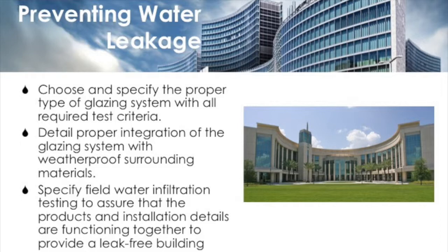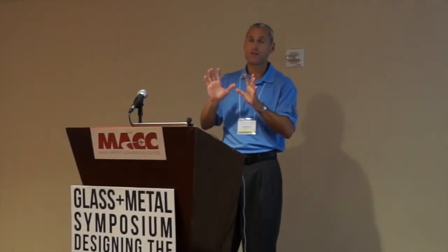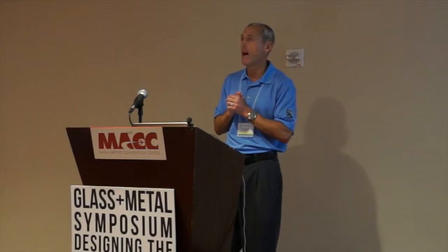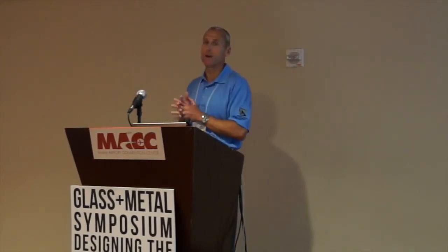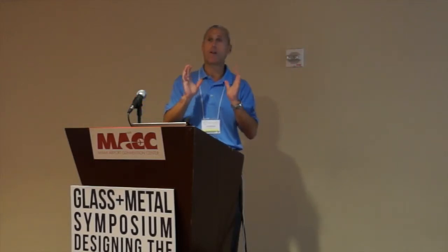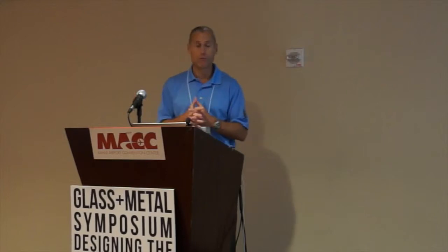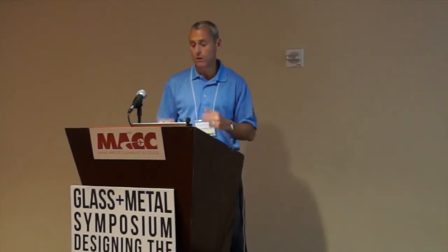And then, in my opinion, and what we do all the time, is specify field water infiltration testing, like the demonstration we're going to see outside. Because the field testing can test the system as it's installed on the job and how it integrates with everything around it. So we're expanding that scope out from just the glazing system to how it integrates with the actual building, how it's going to perform down the road in severe conditions, and we're going to figure out a way to do that so we don't have problems.